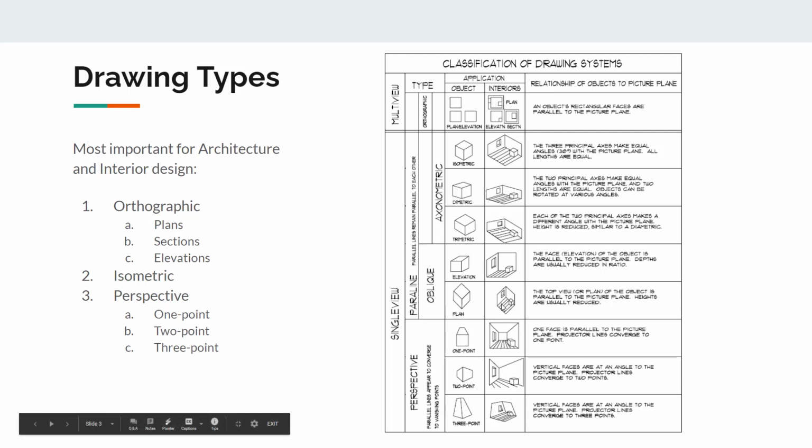1-point perspective, you can see sort of the small image here. It's sort of just one point that converges. Okay, and then moving down, we have a 2-point perspective, which is probably the most common type that you'll be dealing with, and that's where 2 points of the drawing converge at the horizon line. And then a 3-point perspective is similar, except there's just an extra level of distortion where the z-axis or the vertical lines are all converging at a single point, which is somewhere up in here. And as we progress through this slideshow, there's going to be more specific examples, more detailed examples coming up.